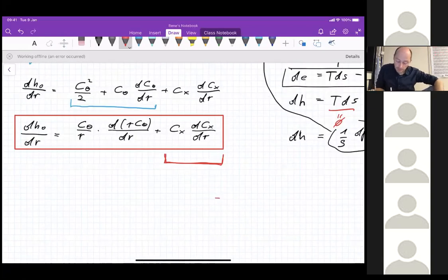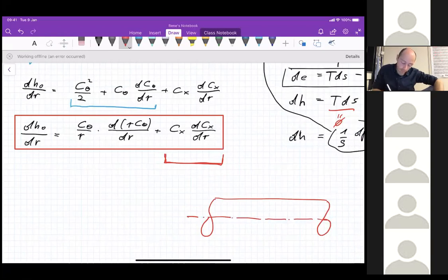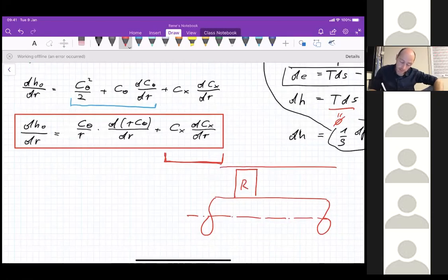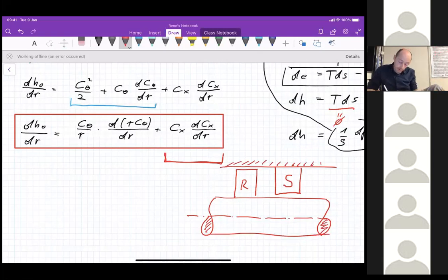So I might have a stage that looks something like that. I have a shaft, and on top of the shaft I have a rotor blade and a stator blade, right? I have the casing, the outer casing, and I have here the stator for a compressor. This is now a compressor, and this is the shaft, and it has a certain rotational speed. So now you can see that the axial velocity, most of the time I would like to keep the axial velocity constant, right?